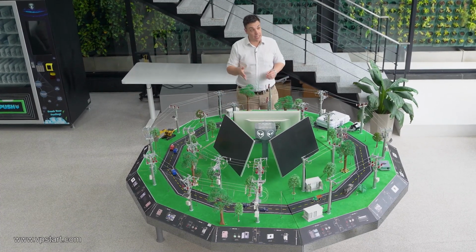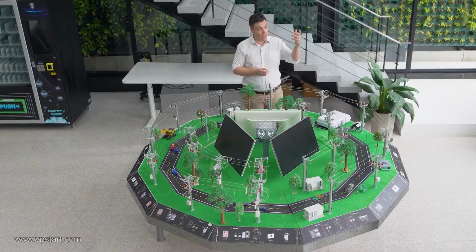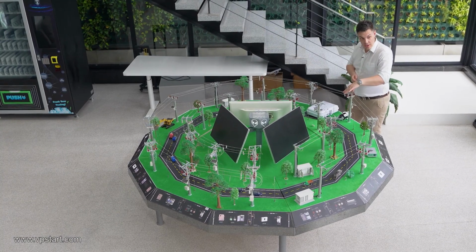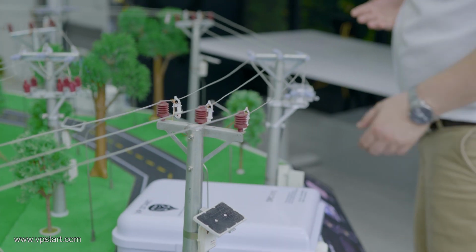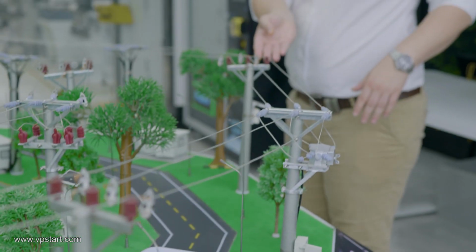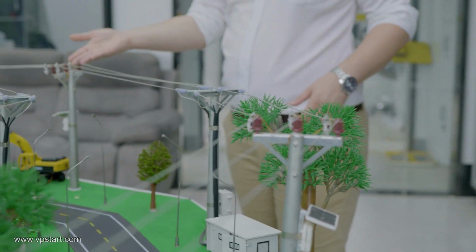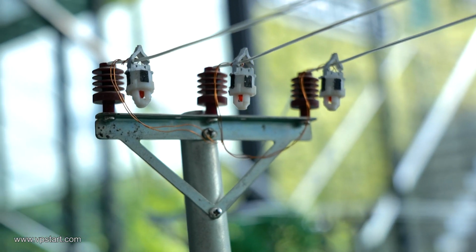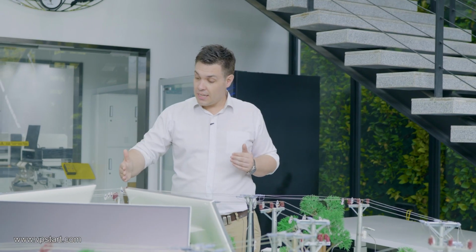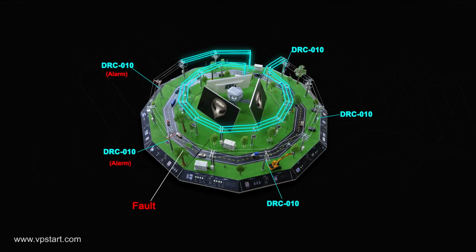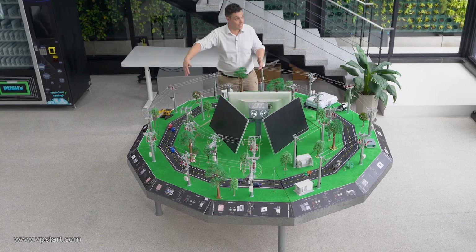When this happens, an alarm gets immediately sent to the RPM grid system for the operator, and also to the admin's mobile phone using our app. From here, we can see the overhead faults are flashing, the lights are flashing at the first point. We can see the same at the second point, but it's not happening at the third point. Therefore, we can deduce that the error is happening between this point and this point. Therefore, we need to isolate this power.